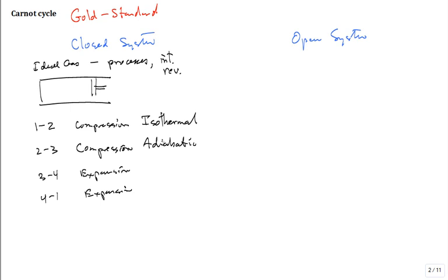Okay? Let me just tell you it's this way. It's isothermal compression, then adiabatic compression. Then, guess what we're going to have? Expansion. Is it going to be constant temperature, isothermal expansion, and then adiabatic expansion, or the other way? It'll be the first one. It'll be isothermal expansion and adiabatic expansion. How does this make power? How is this a heat engine?